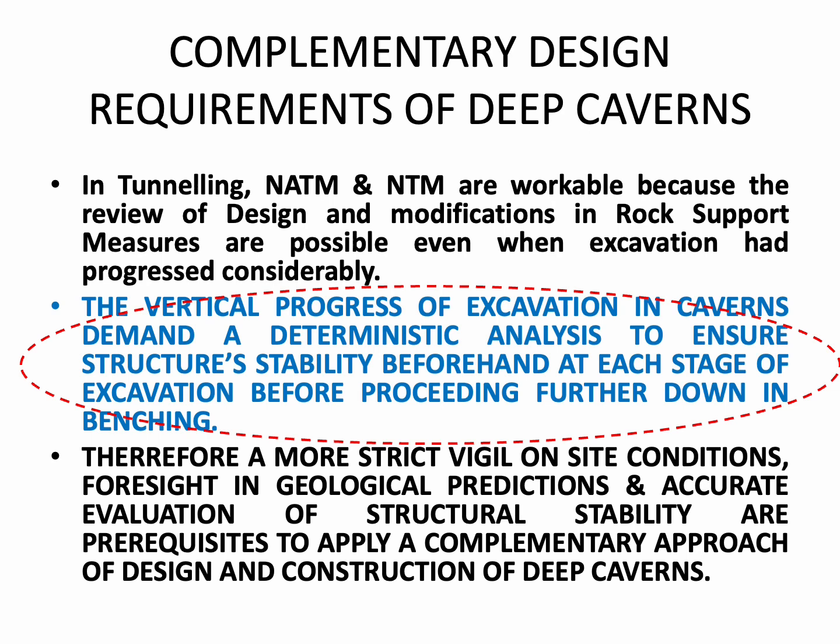But in very deep and large caverns, the excavation is progressing vertically downward. So the vertical progress of excavation in caverns demands a deterministic analysis to ensure the structure's stability beforehand at each stage of excavation before proceeding further down in benching.